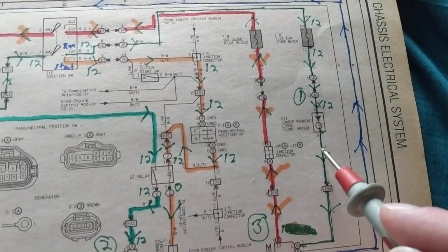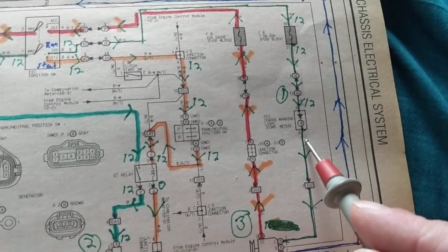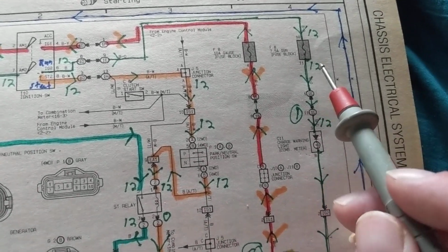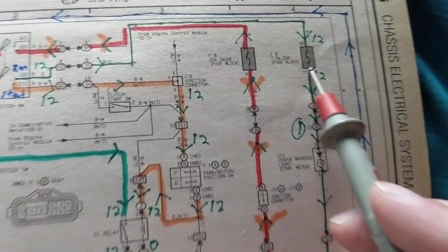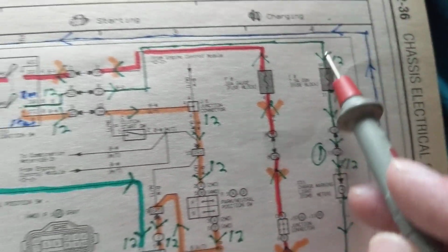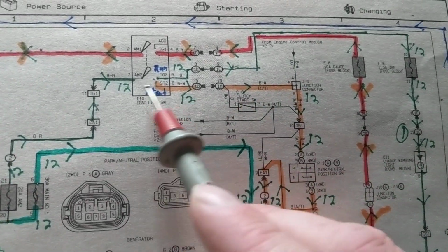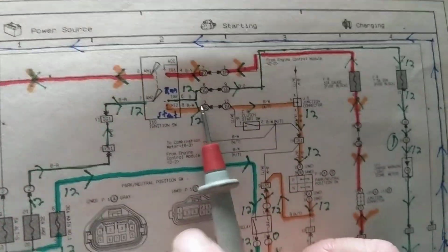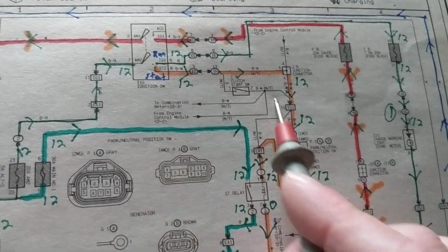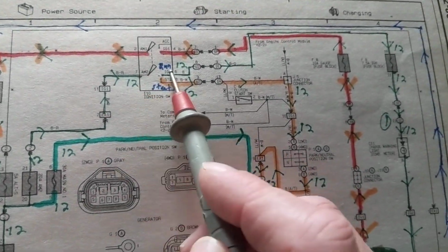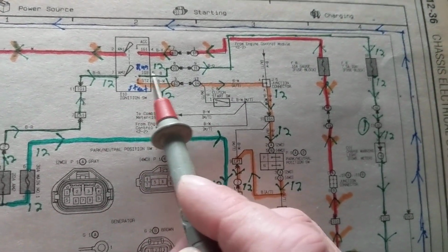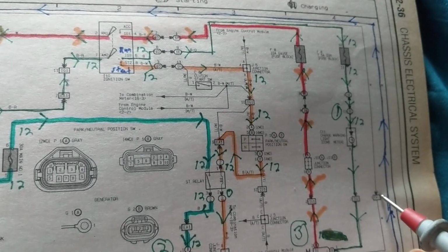Let's delve into it much deeper. The fact that this is lighting, the bulb is lighting, is telling me what? In this case, it's telling me that this fuse is good. What else is it telling me? It's telling me that the ignition switch is good, at least in the run position. I don't know about the start position. I didn't crank yet. But I know at least in the run position, this is good. How do I know? The bulb is lighting.